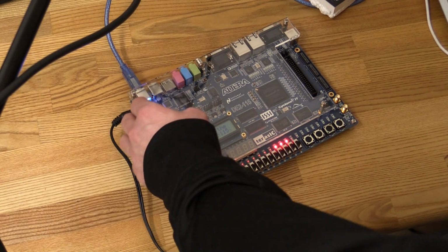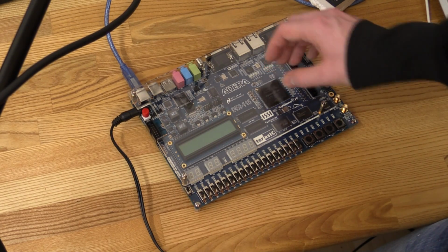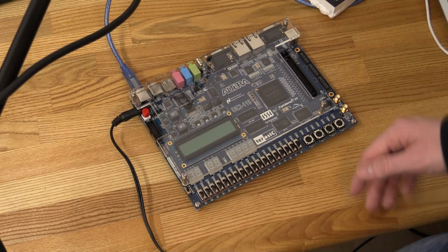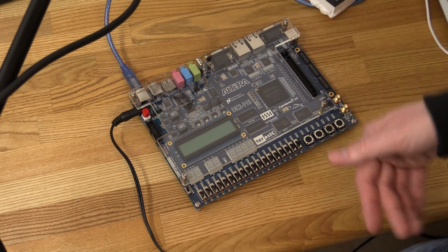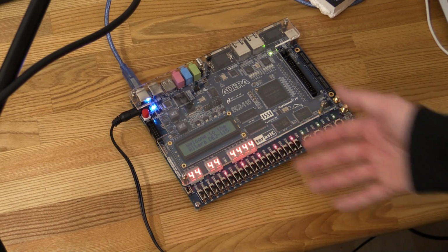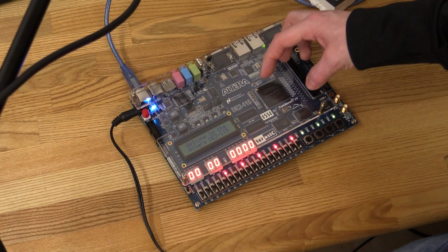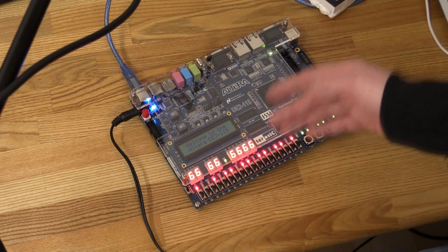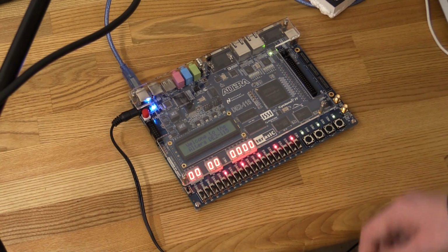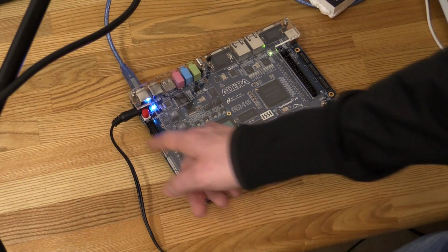And you will also see it again and again when we write the code for the clock. Just to demonstrate that the program is only in the FPGA, and the FPGA will die completely when you turn the power off. You have to reprogram them every time you power them up. So when we power it up, we will be back to the standard program. We can though flash our configuration into the flash memory so that it will load that every time it starts up. But just for testing and trying out random stuff, this is easier.